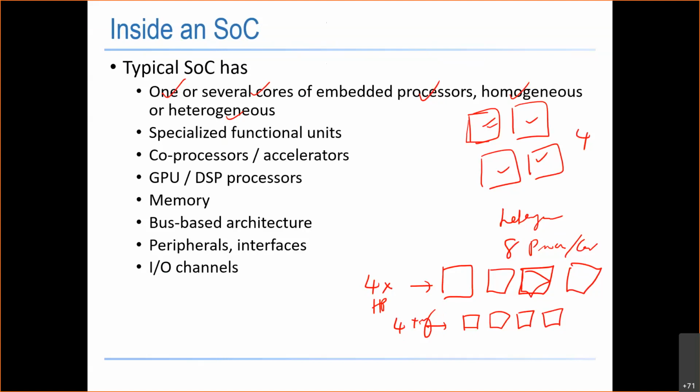The reason we have that is because when you play games, you want high performance, so we use the high performance CPUs. But when your phone is idle, and you're chatting or doing simple web browsing, if you turn on the high performance processor, it's going to consume too much electricity, too much battery, too much energy, too much power. So we use a smaller CPU core for tasks that do not require high performance. This way you get a good balance between performance as well as energy saving. So you get the best of both.